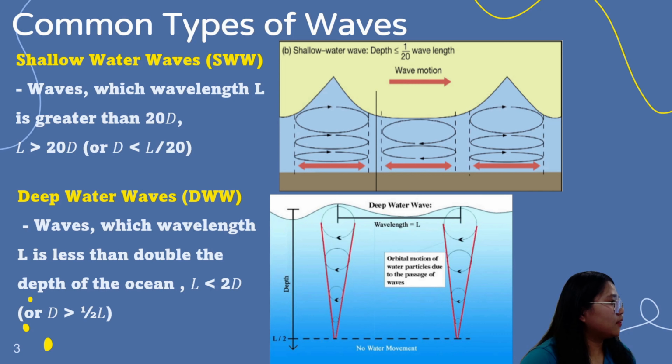Actually, I would say that's almost like a sketch for a non-linear wave. But I guess waves start becoming non-linear anyway, so you may have no control whatsoever on that. That's why you might have seen such a pronounced crest and not that pronounced a trough, and then there comes your next pronounced crest, and the second following stroke comes in. So that in the end you generate the shallow one. But here it was the same wave height and water depth. Didn't see much if you keep it linear.